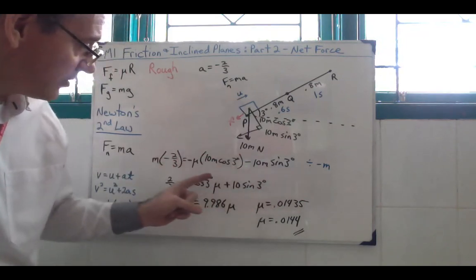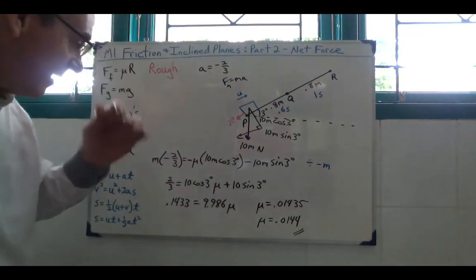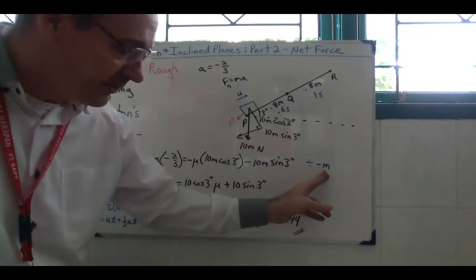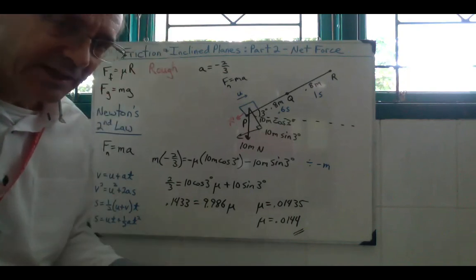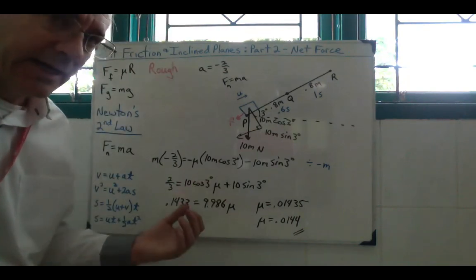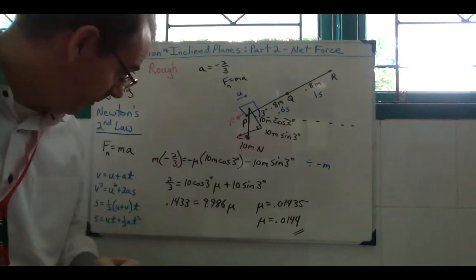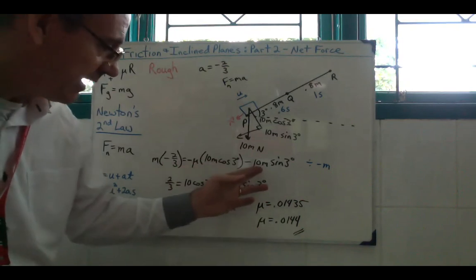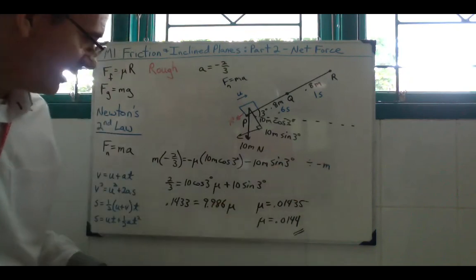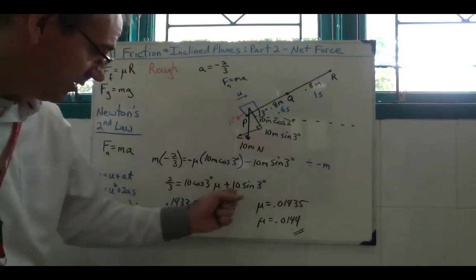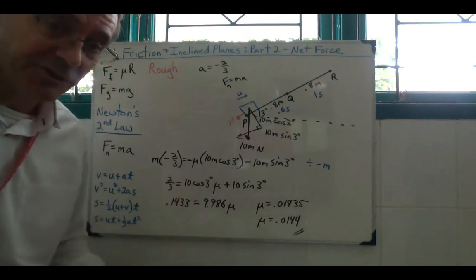So this one here is a little tricky because it's got those two unknowns, but only one equation. However, you can divide out the variable. Normally, you don't want to divide out variables. In this case, it's okay simply because you don't need that variable to solve for it. So you could have also factored it out, and then when you divide it, it would cancel. Either way, just divide by a negative, a little easier, and then solve for mu. Got some trig stuff in there. Make sure your calculator's in degree mode.